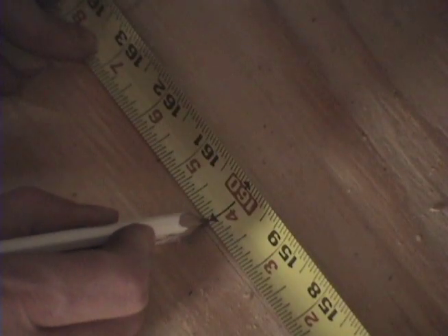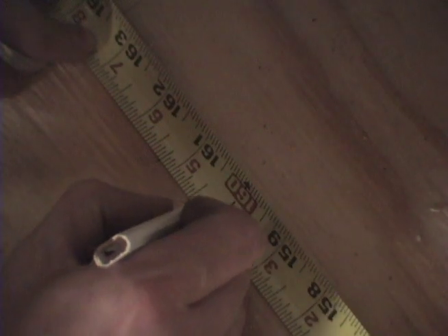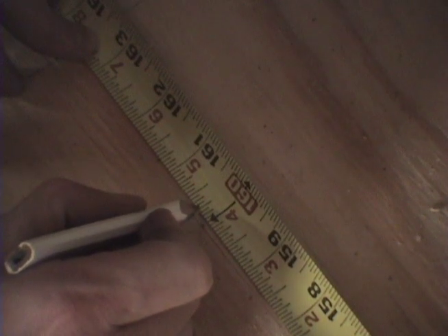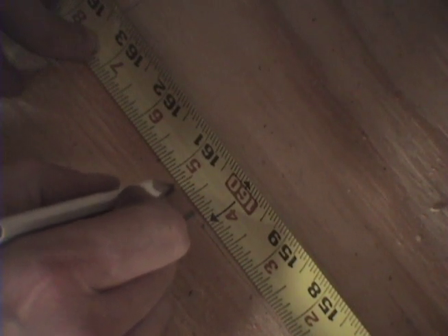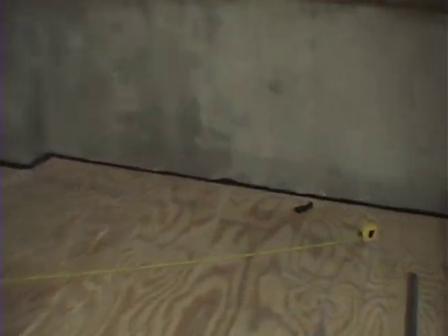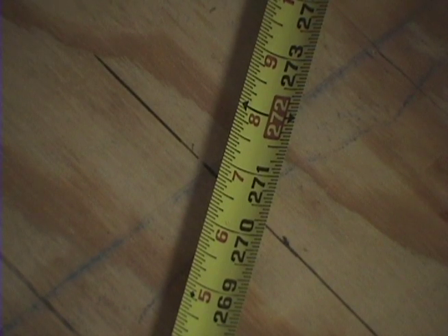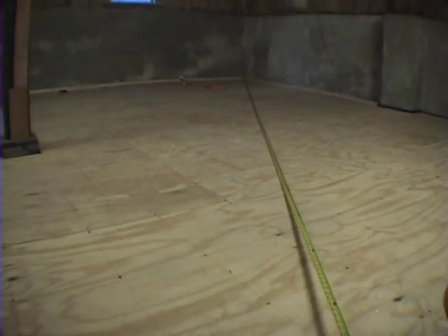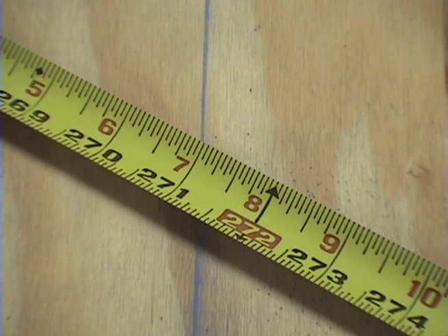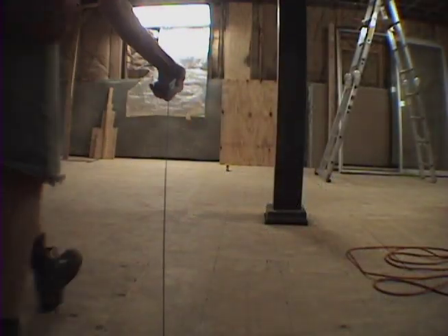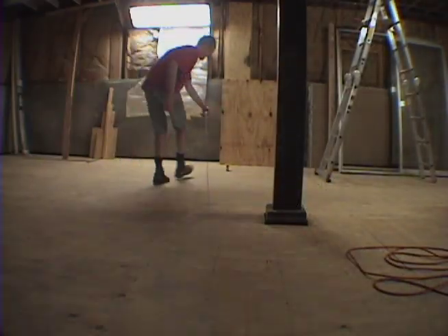Once one wall plate is in place, then we measure the actual width of the room, in this case 160.18 inches. Don't forget to account for the 1/2 inch drywall on 2 sides. Add this to your measurements so that the inside of the room is the right measurement. Now we can measure diagonally from that corner to the opposite corner where the front wall plate is going to be. For my room, this is 271 inches. Then I can make the same measurements from the other corner, and then the 2 walls will have the same angle. Then we can snap a line on the floor, and we have our guide for the installation.